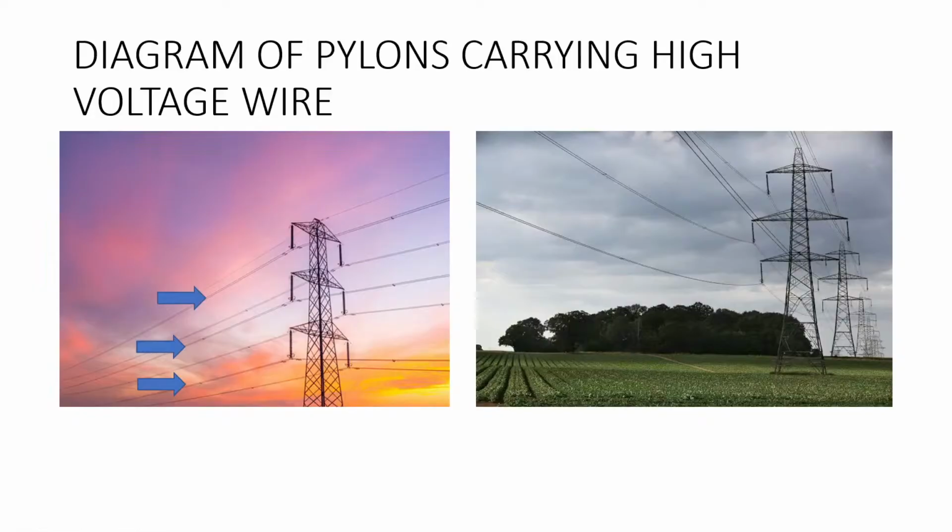So if, for example, the cable is going to be 20 meters, and you are going to be seeing a pylon at every 1 meter, it means that you are going to be having how many pylons? 20 in number. I hope that makes sense. So you just get the total length of the cable divided by the center to center spacing, and you get your number of pylons.